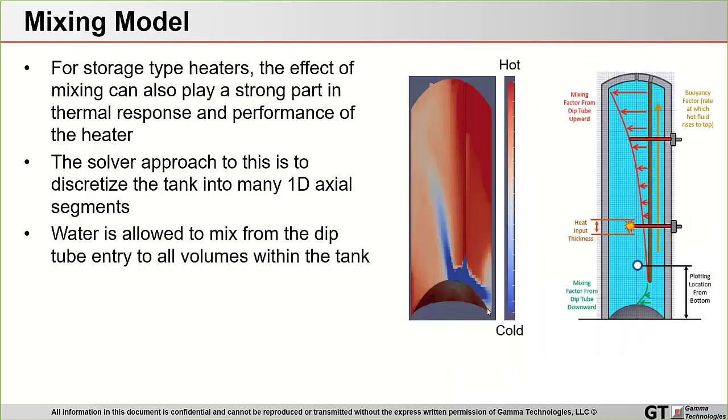And then the next effect also, particularly for storage type heaters, is the effect of mixing. And this can play a strong part as well in the thermal response and performance of the heater, where you can see, for example, in this case, you've got some cold water that's being shot out of the bottom of the dip tube, and it's flowing up in a very streamlined fashion here up to the outlet of the water heater.